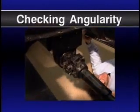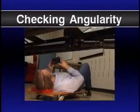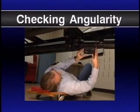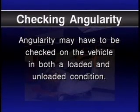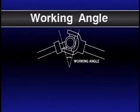Once you are certain the driveline is in phase, the next step is to check the angularity of the driveline. First, you need to measure the angles of all the U-joints, then compute the angularity to determine if it's within tolerance. Angularity may have to be checked on the vehicle in both a loaded and unloaded condition. But first, let's discuss installed and working angles and how to measure them.